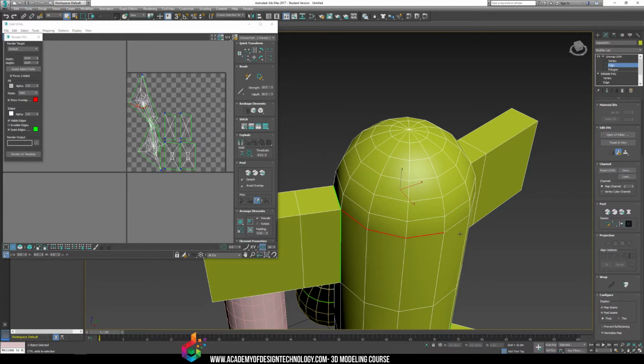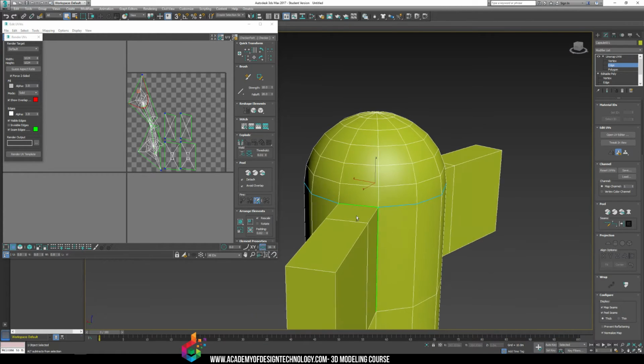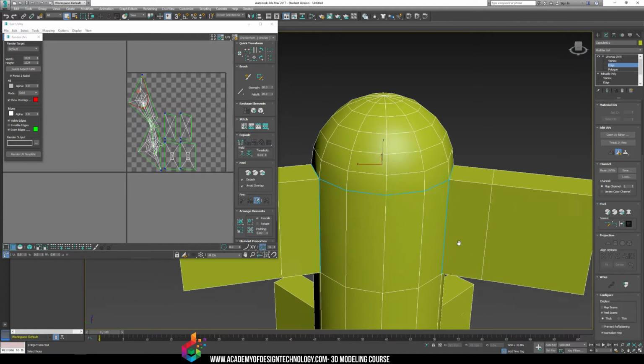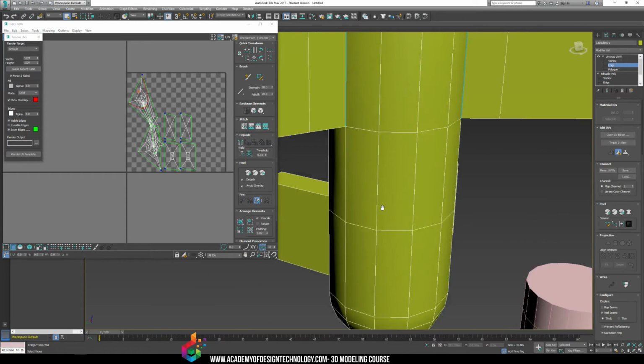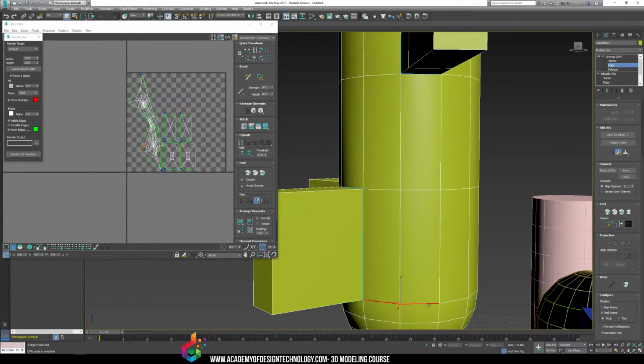And go around and add a seam line here. Now, if you can't see your old blue lines, go down and take off map seams. It'll show you only peel seams, which are these blue lines here. So I cut off the top part of my capsule, and I'm going to do the same for the bottom part of my capsule. I'm going to cut this off too.